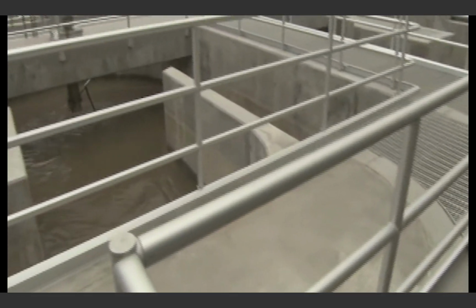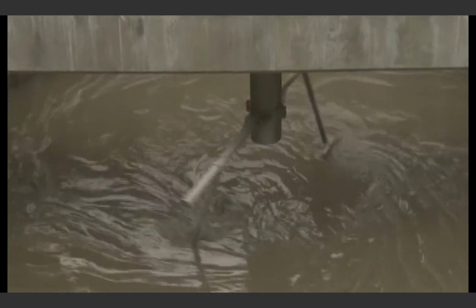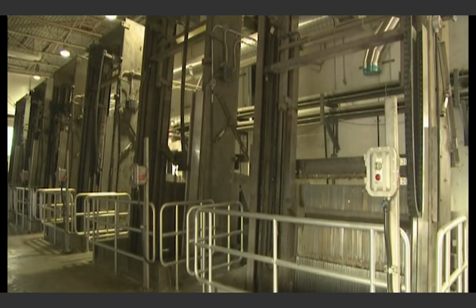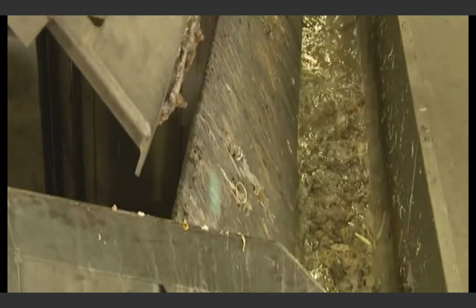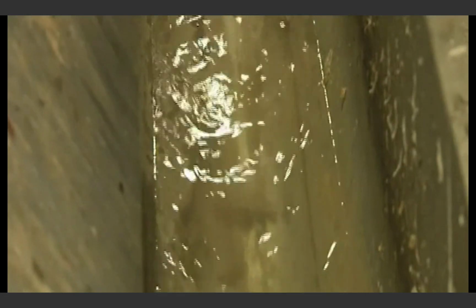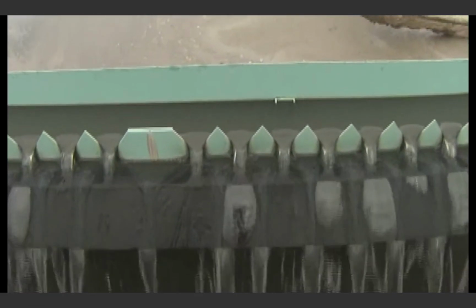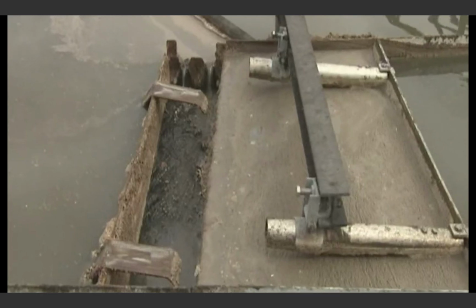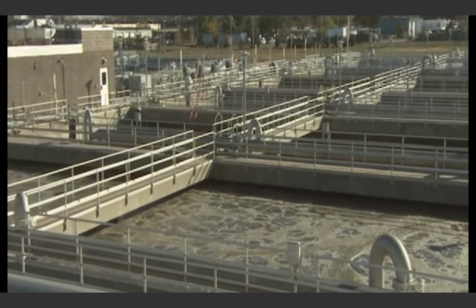Pre-treatment processes equalize flows and loadings, and precondition wastewaters to neutralize or remove toxics and industrial wastes that could adversely affect sewers or inhibit operations of publicly owned treatment works. Preliminary treatment processes protect plant mechanical equipment, remove extraneous matter such as grit, trash, and debris, reduce odors, and render incoming sewage more amenable to subsequent treatment and handling. Primary treatment employs mechanical and physical unit processes to separate and remove floatables and suspended solids and to prepare wastewater for biological treatment.